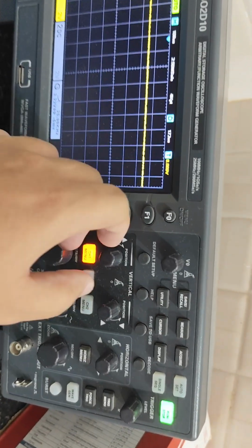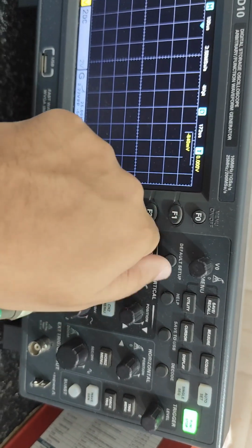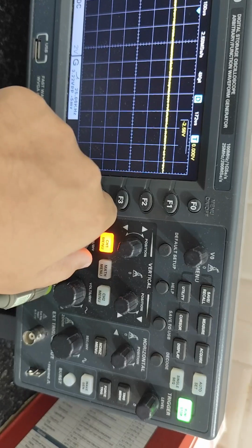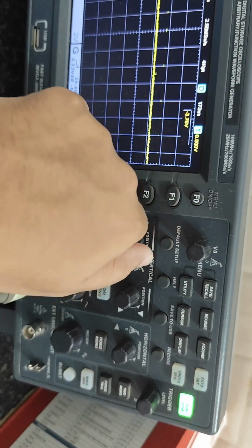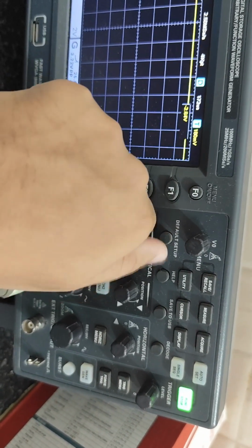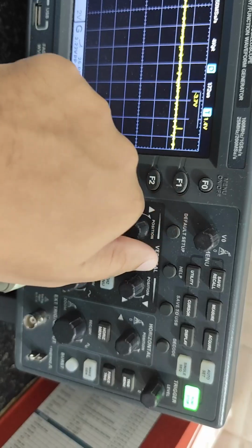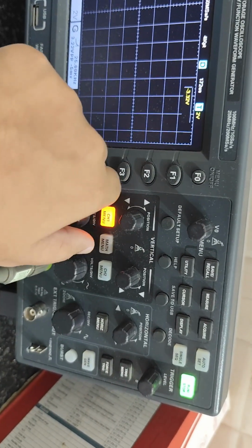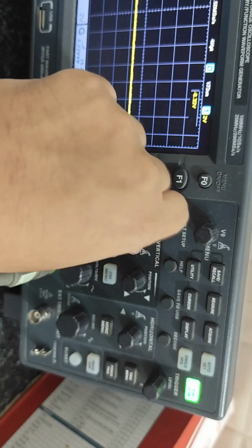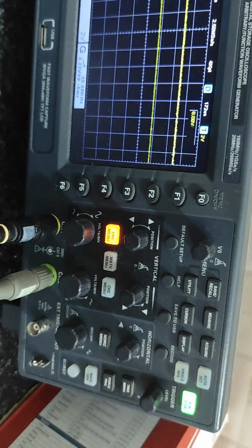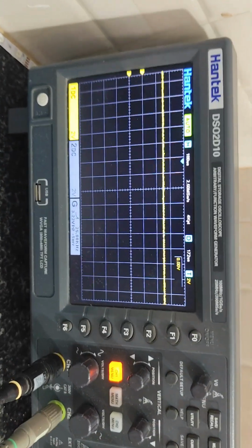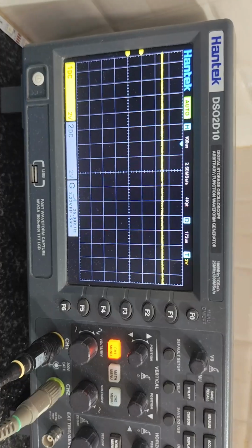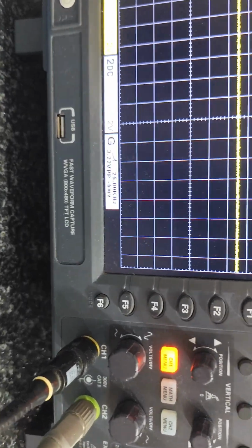And even if we zoom in and out a bit, we cannot see much of a ripple. It's basically just raw voltage. And if we go to the nominal, let's reset the 0 position. So this is the DC coupling, and now we'll shift to AC.